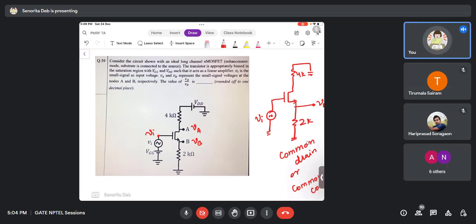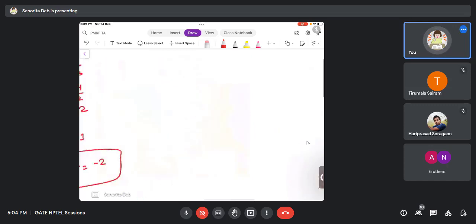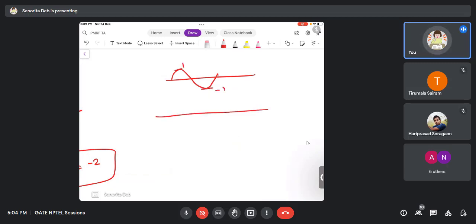And when you put the oscilloscope terminal at VB with respect to ground, you saw something else. So basically, if your input from function generator is like this, 1 -1, then your oscilloscope at VA will show 2 -2 and VB will show us 1 -1.